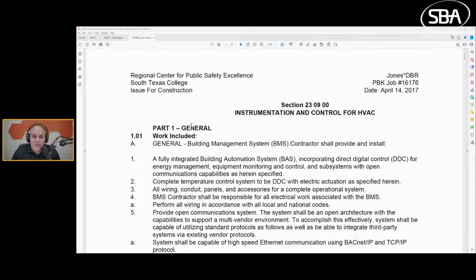We have our voltage inputs. These are volts DC, typically 0 to 10, 2 to 10, 0 to 5, 1 to 5, etc. volts DC. That's typically for powered sensors, either externally or internally, things like humidity sensors, etc. And then we have our 4 to 20 milliamp.